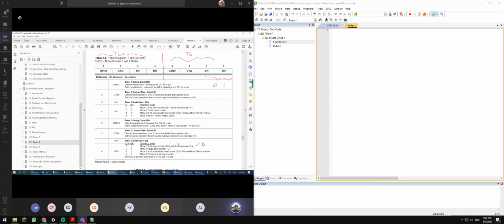Whereas 8-bit auto reload mode means that you no longer need to reload your value of timer. Let's say TH0 and TL0 is 1, 2, 3, 4, we no longer need to reload this value when you come to the interrupt service routine. However, it's just 8-bit only, so it's not very useful, because you create a very large counter value. That's the reason we still prefer 16-bit timer settings.